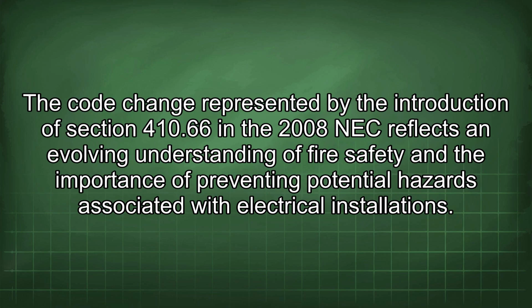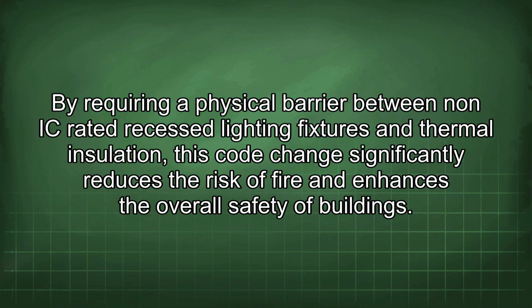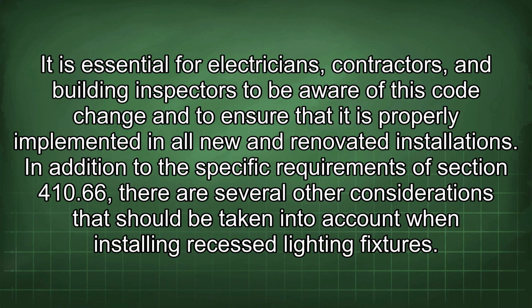The code change represented by the introduction of Section 410.66 in the 2008 NEC reflects an evolving understanding of fire safety and the importance of preventing potential hazards associated with electrical installations. By requiring a physical barrier between non-IC rated recessed lighting fixtures and thermal insulation, this code change significantly reduces the risk of fire and enhances the overall safety of buildings. It is essential for electricians, contractors, and building inspectors to be aware of this code change and to ensure that it is properly implemented in all new and renovated installations.